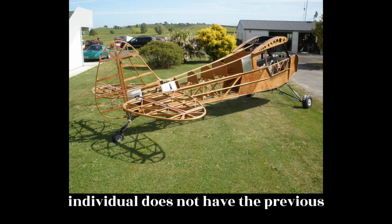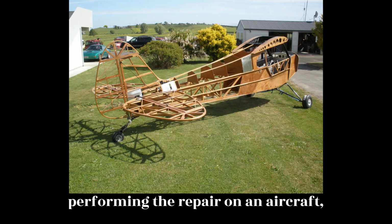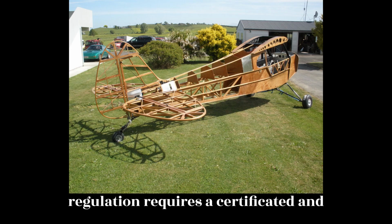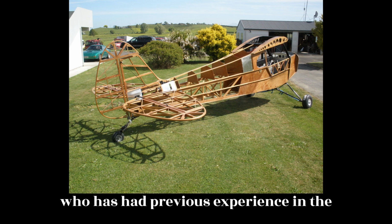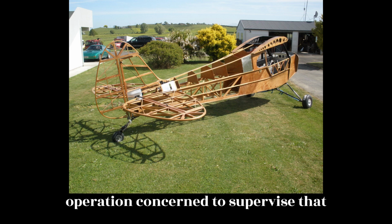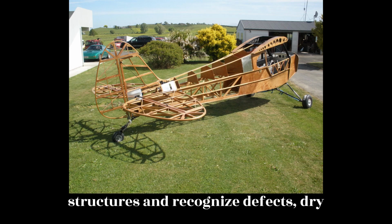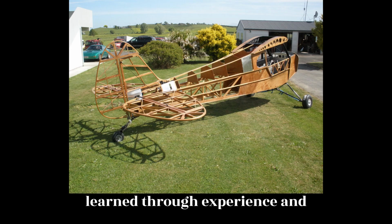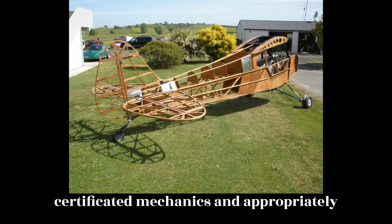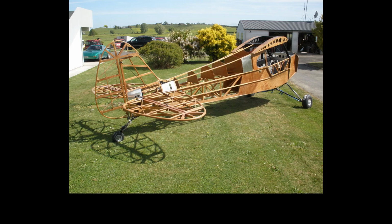This means that if an individual does not have the previous aviation woodworking experience performing the repair on an aircraft, regulation requires a certificated and appropriately rated mechanic or repairman who has had previous experience in the operation concerned to supervise that person. The ability to inspect wood structures and recognize defects, dry rot, compression failures, etc., can be learned through experience and instruction from knowledgeable certificated mechanics and appropriately qualified technical instructors.